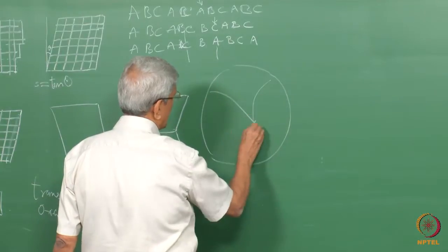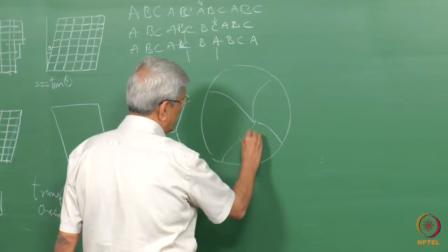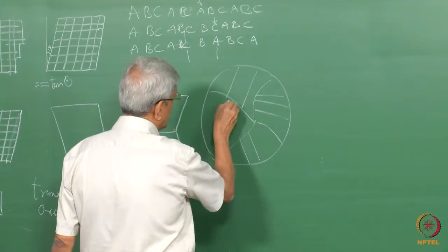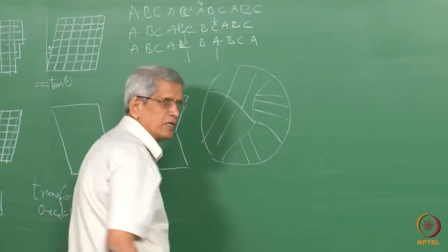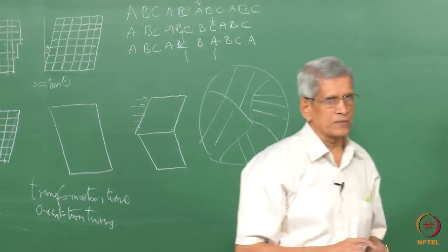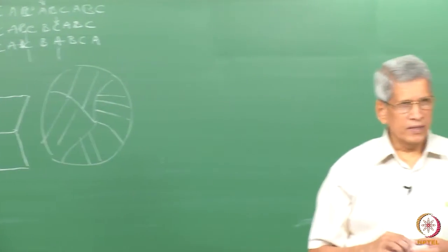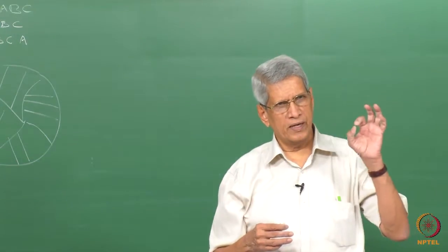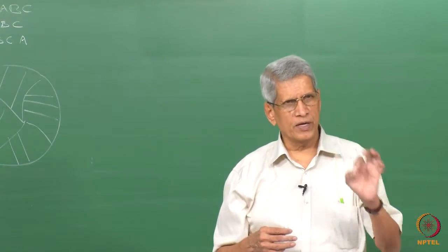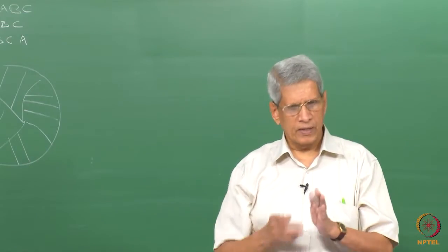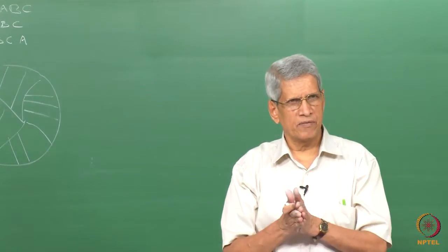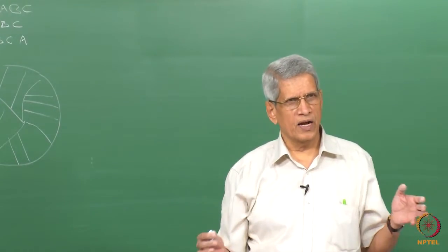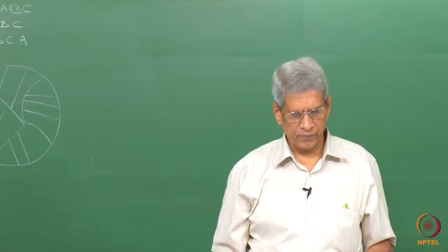In the grains which are connected like this, within them we find lots of regions like this which are related. These are all twins. These we call annealing twins. That is, when defect free, dislocation free regions grow from the completely deformed region, the atoms arrange themselves in such a way that sometimes the stacking sequence is changed. Those regions we call annealing twins.